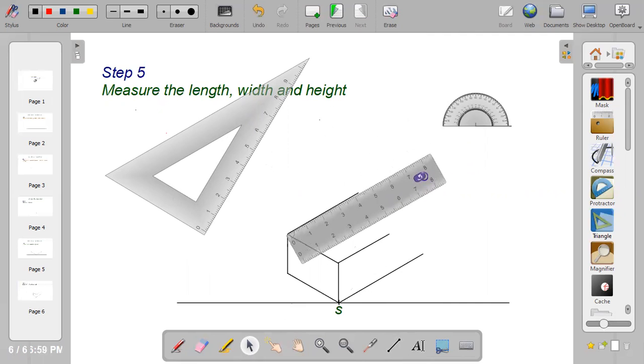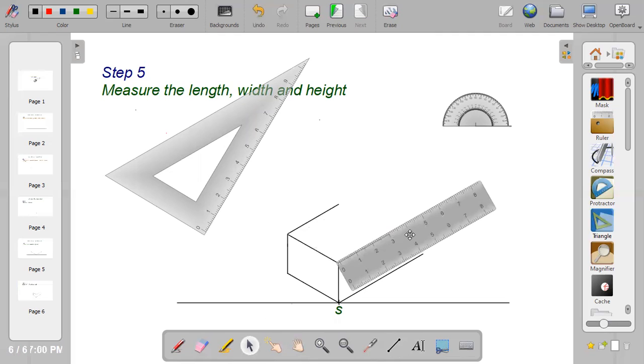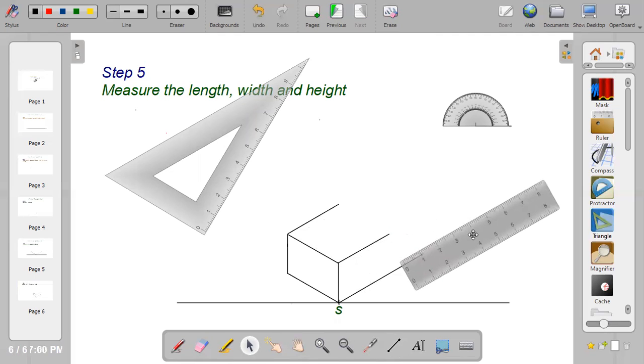Okay, I have an extension. I will erase it, erase the extension. So I have 30 mm. Then you can also confirm other lines to be sure you're on the right path. This is also 30 mm. Since I have two equal lines, all I need to do is to join them together with a straight line. So join the two lines with a straight line.